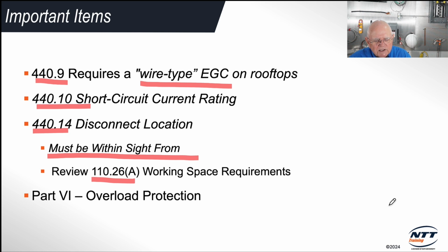And then Part 6 covers overload protection. And there's lots of information in Part 6 on overload protection of this equipment. They're hermetically sealed. It's either thermally protected or it's thermally protected by a system, one or the other. So it should not be an issue for us. Once again, follow the information on that nameplate.